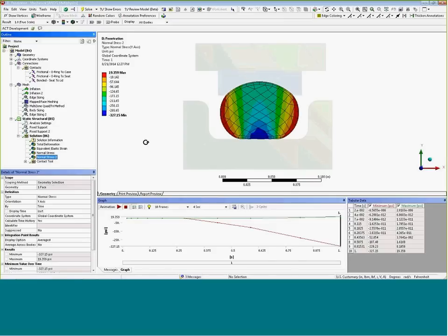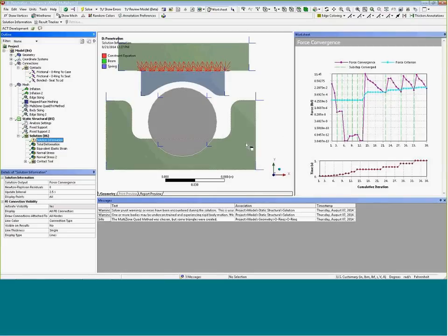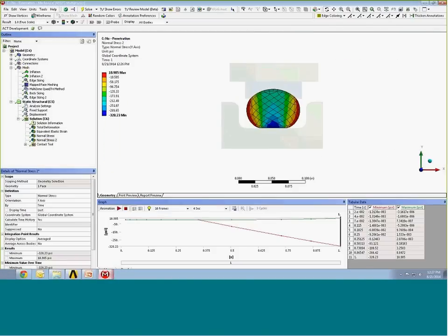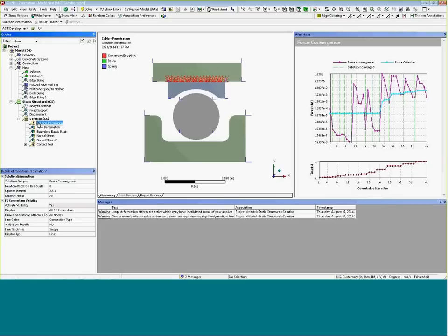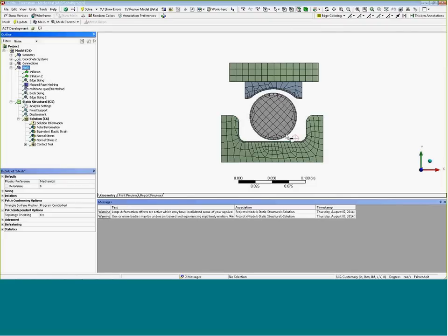And if we looked at this in terms of how easy it was to converge, well, this model took 38 iterations to converge, resolving out the interference fit. And then modeling it this way, it took 42. So, it depends on your settings and things, but this is essentially identical convergence and identical answer, but solving the problem two different ways. I will say, though, that solving the model this way is generally more difficult to get to converge,